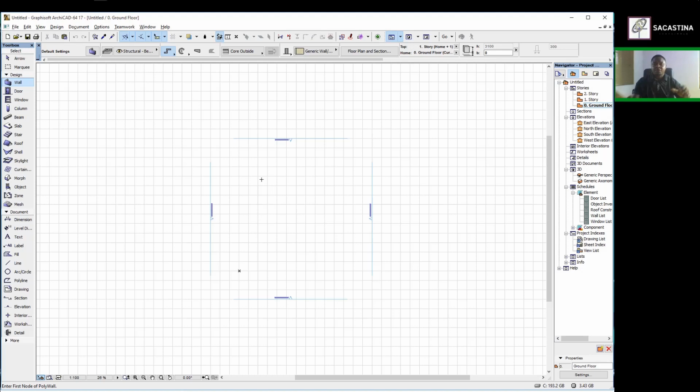Now this is our ArchiCAD fresh page, default page. It doesn't have any shortcuts, doesn't have any settings, nothing at all. So first of all, we'll talk about saving a file. Once you've opened your ArchiCAD file, whether version 12 or 24, from later version to earlier version, what you first of all do is go to your File menu.